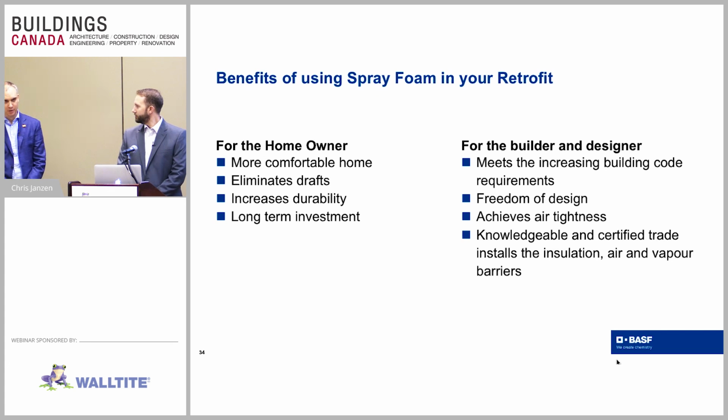In a properly built, properly constructed building, no. The double vapor barrier is not a concern because there shouldn't be any moisture. You don't want moisture during construction before you put your 6 mil poly up anyway. The spray foam's there, so there shouldn't be any moisture to begin with. You put your 6 mil poly up, and you're not going to have any moisture in there anyways. That's just conditioned space, warm room temperature space. So it's basically redundant to do it, but maybe. Yeah, exactly. It's probably $1,000 for 6 mil poly. How much effort do you want to put in to combat the building official on that?